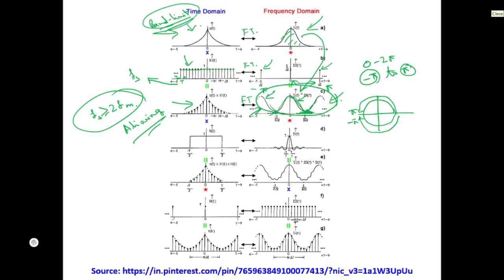Okay. First we did the band limiting. When we are sampling in the time domain, we are limiting the frequency component. Now when we are trying to sample the frequency component, we will be limiting the time domain signal. So we will be multiplying it with a time domain filter. That means we will be taking only a portion of the signal, okay, and the rest of the signal components are put to 0.